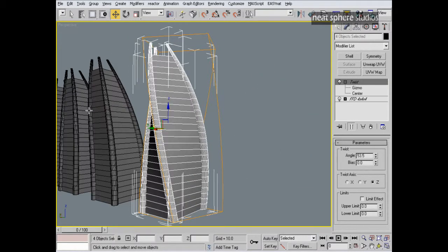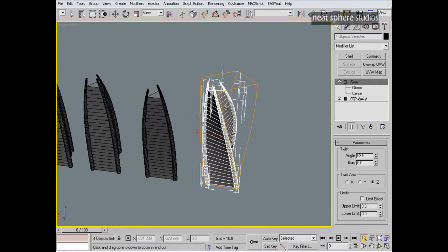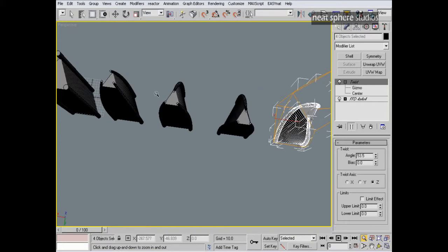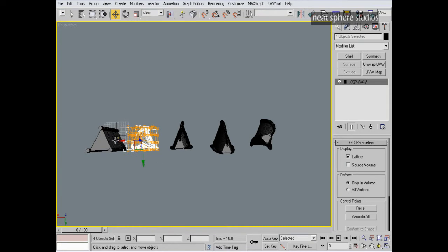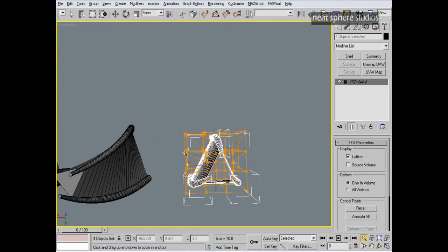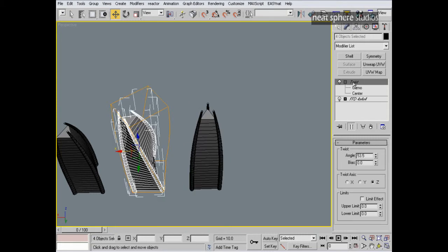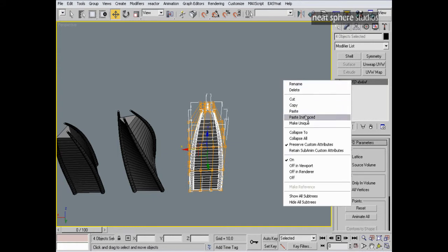So actually that's looking quite interesting. In actual fact, when I look at it, the twist there, I think, well, maybe I want that triangle to be more in the center, very much like it was with this particular set. So we'll move another one along again. What's great about 3D Studio Max is that I can grab this twist and I can copy it. I can grab a whole bunch of stuff over here which was effectively the same objects, and I can paste.